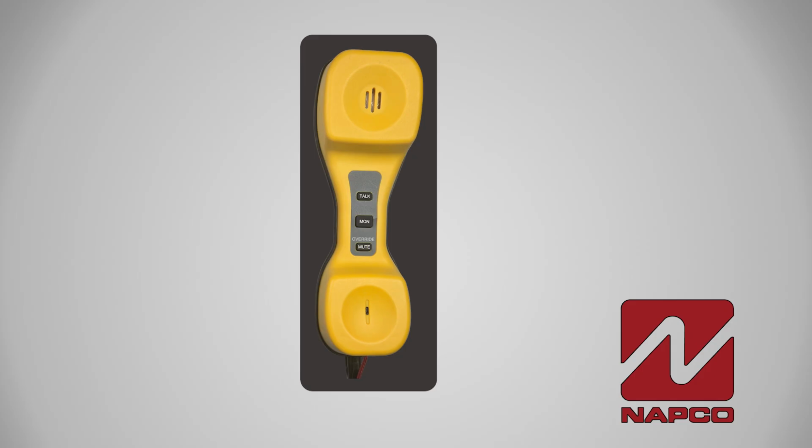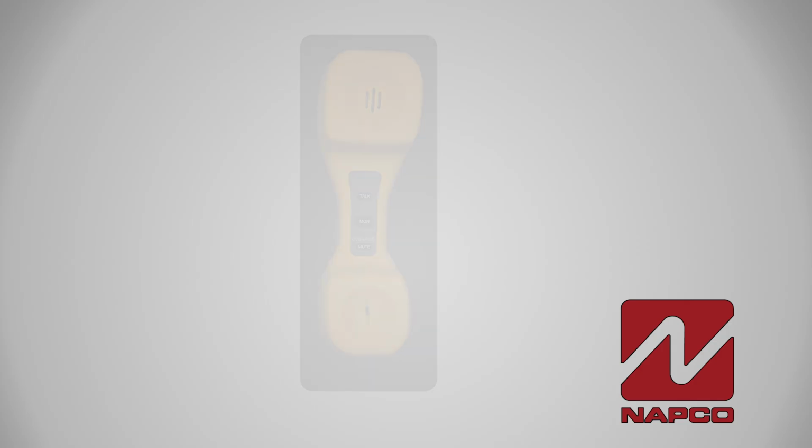An okay butt set with a built-in speaker can run you about $200, but it's well worth it and it'll pay itself off quickly. You can troubleshoot with a butt set by tapping the line between the alarm panel and the radio. Now, depending on which model Starlink you have, there will be two possible types of telco connections.